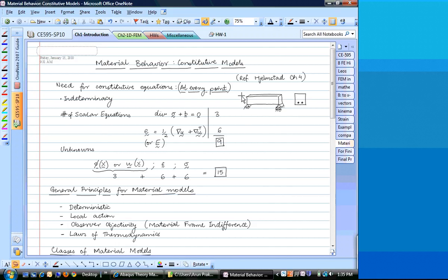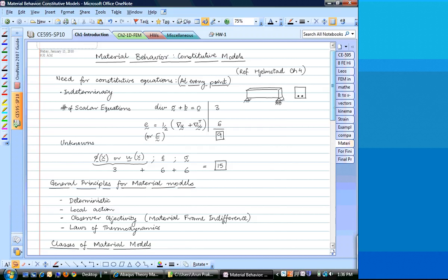Now, at the same time, you also need to realize that this material model can be different at different points of the beam. So for example, this is my bridge beam, and it has some reinforcement towards the bottom fibers. So the reinforcement has a material steel, and the rest of that is concrete, and you need to distinguish between those two types of materials also within your body.